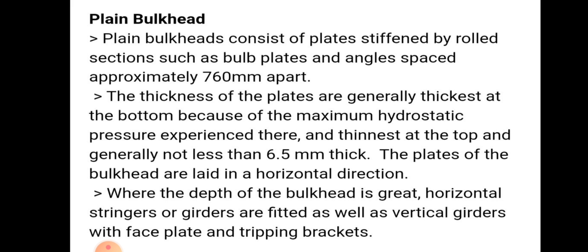Thickness of plates is generally thickest at the bottom because of the maximum hydrostatic pressure experienced there, and thinnest at the top, generally not less than 6.5 mm thick.